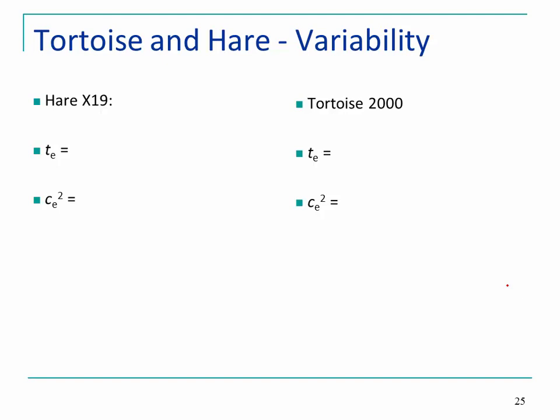So if we look at the coefficients that we have for both of these machines, we can compute the mean process time as follows. This is T0 divided by the availability. So in this case, that's 15 minutes divided by 0.75. So this is 20 minutes. So if you take into account the availability, that is the effective time of processing a part.